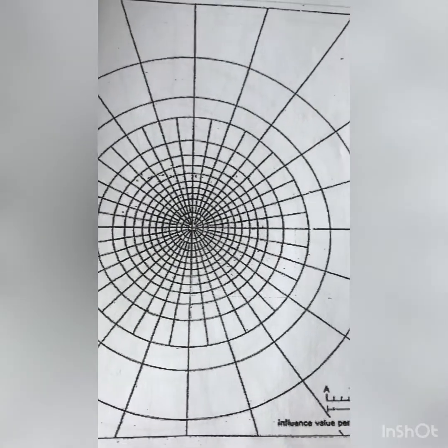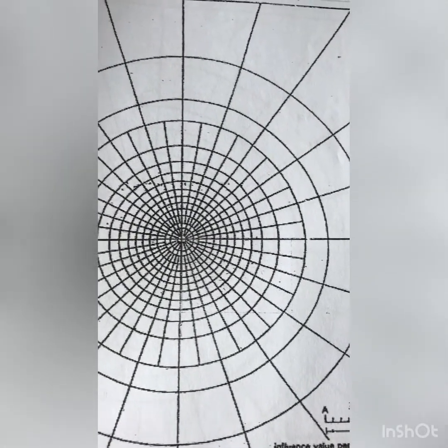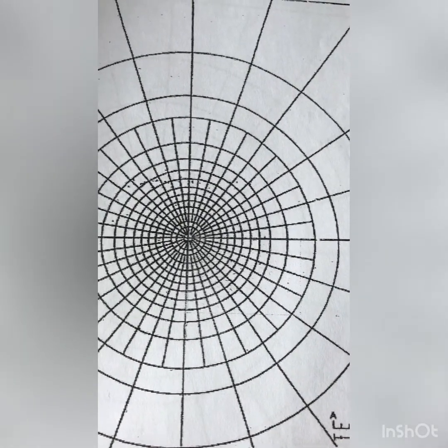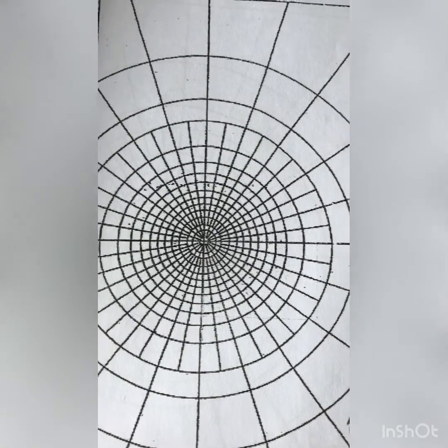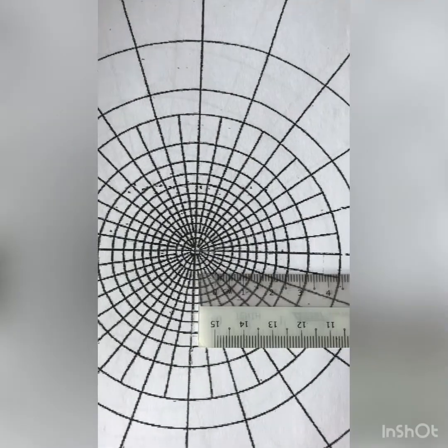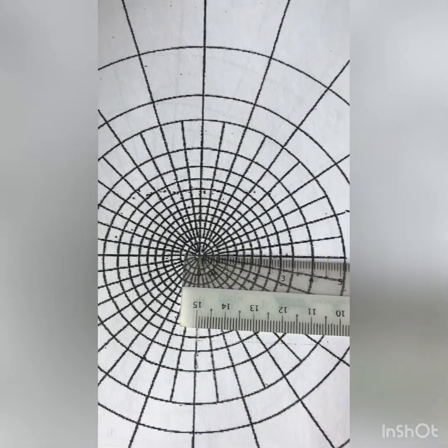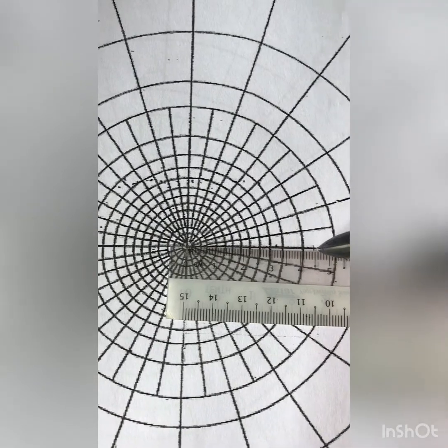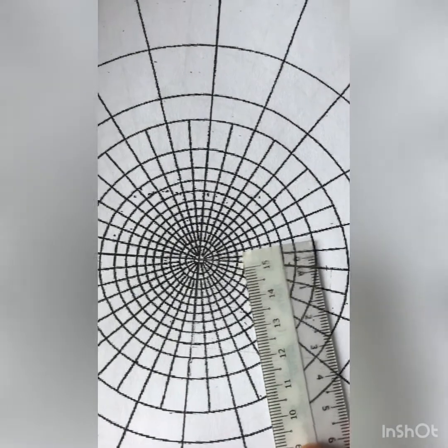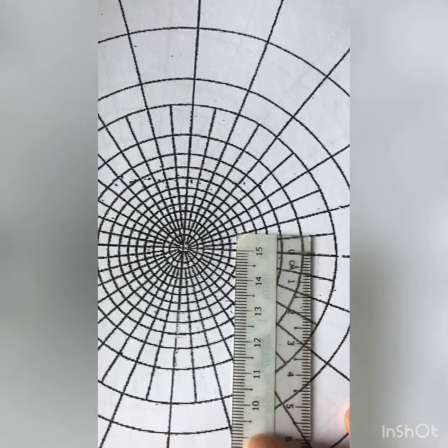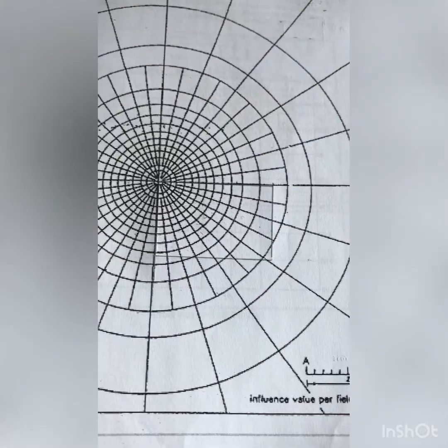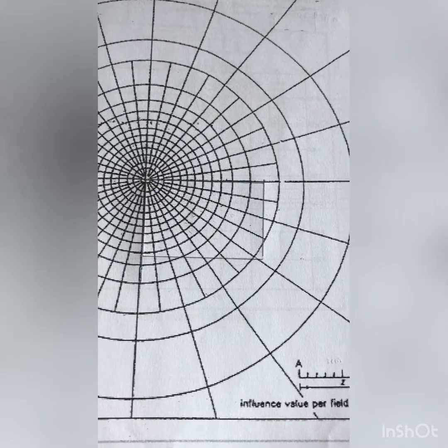Alright, so now we can sketch foundation B on the Newmark chart. The centimeter units that we got, we will use in this. So we use the ruler and look at the question. So we get 4.5. So we measure it and take it, and then we measure 3 centimeter. Here, so we take it. Alright, this is foundation B that I get.